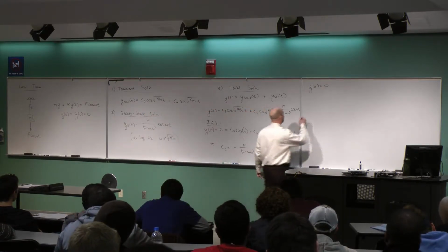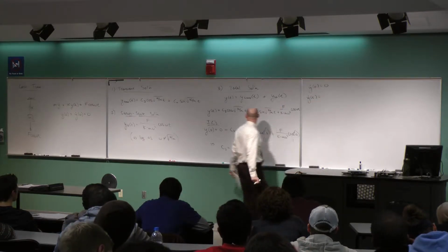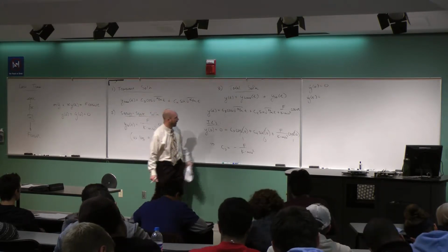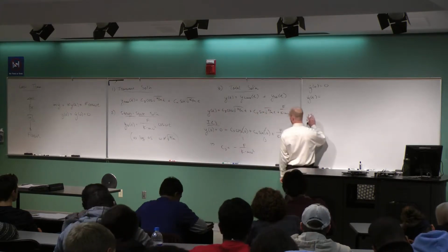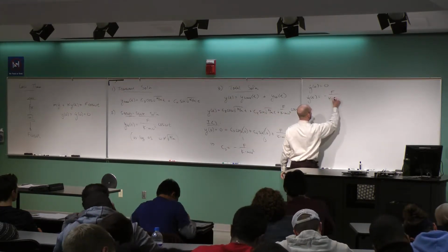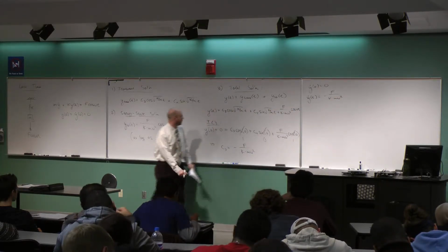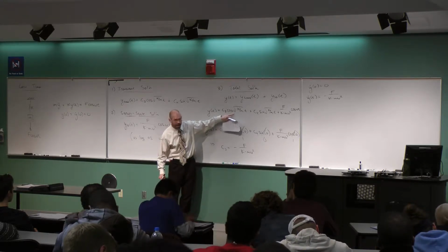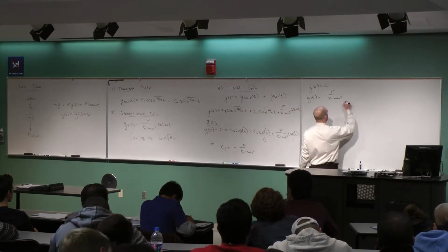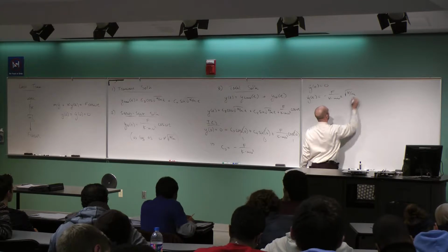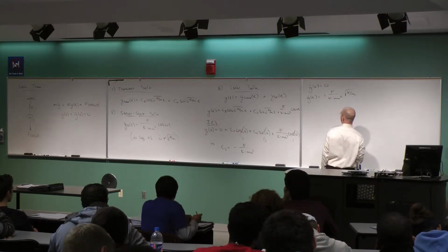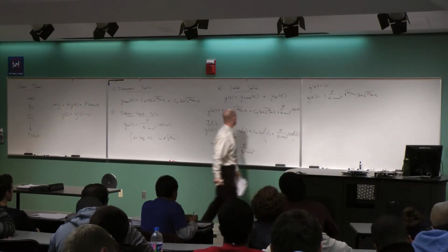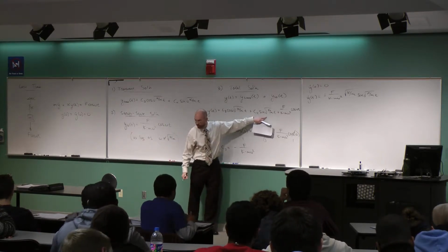So let's take y dot first. y dot of t would be equal to what? So I got to take the derivative. The first term, I already have the C3, so I can put that in. I'm going to have negative f divided by k minus m omega squared. That was the C3 I already found. And then I have the derivative of the cosine, which gives me what? Negative sine, and this root k over m comes out front. So I'll get root k over m out front. The negative comes out front, so I'll make that a positive. And then I'm going to get a sine function, root k over m t. That's the derivative of the first term. Second term, I got C4. Derivative of the sine is what?